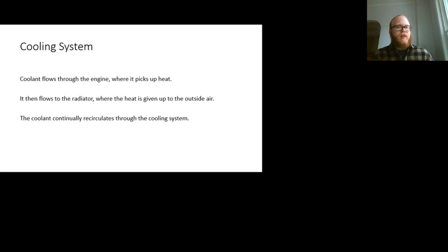Our cooling system is the source of heat in the vehicle. We're going to talk about refrigeration later. So coolant flows through the engine where it picks up heat. It's picking up heat to try to keep my combustion chamber at the right temperature consistently, so we have great combustion every single time. But as much as 2/3 of the energy from fuel can be wasted as heat. And so we're trying to figure out ways to use this heat to do other stuff, so we're not wasting as much of our fuel energy. And one easy way to do that is take that hot coolant, send it through a radiator in the dashboard, and heat the air up so that we're not shivering.